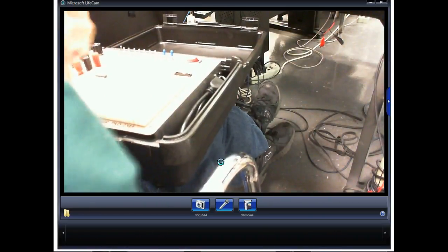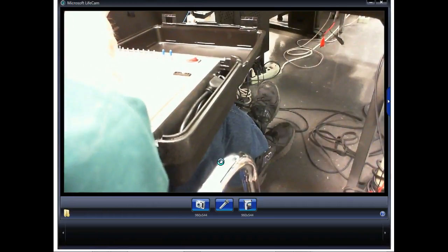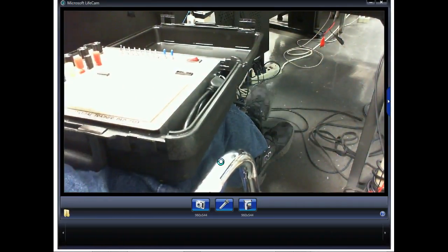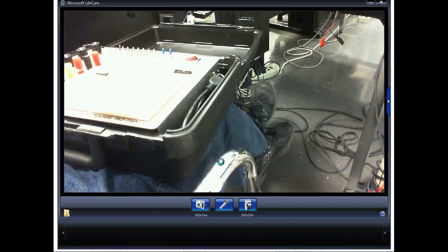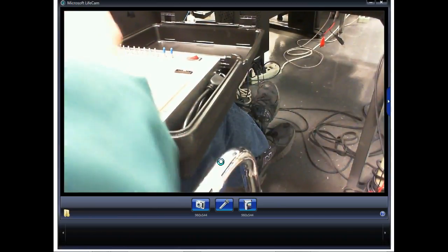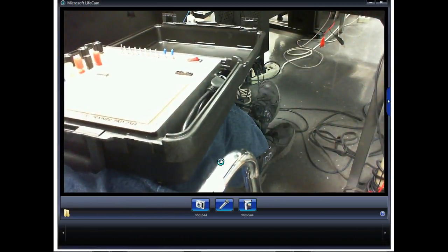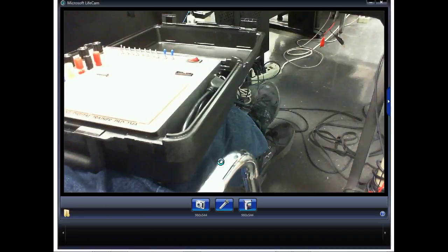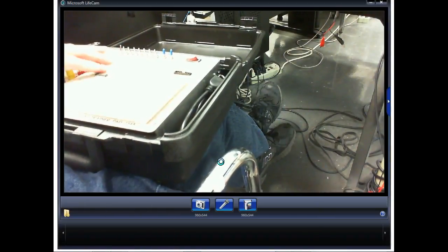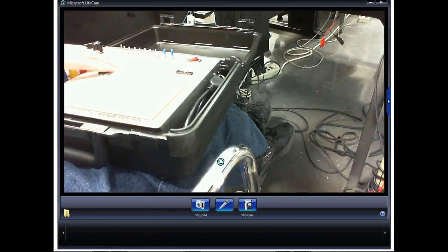So I don't want to come over here and see 15 wires hooked up to the plus 5 volts. We have people that see that. They say, okay, it goes to plus 5 volts. Then I got to run it back to that stop that says plus 5 volts, and not realize they got plus 5 volts sitting 2 or 3 millimeters from where they're running. So what you do is you do all your jumping out in the circuit.